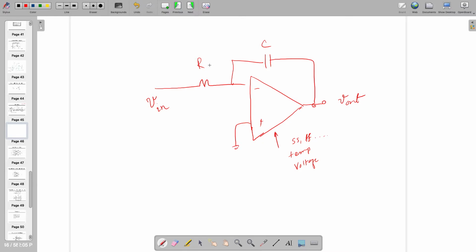Now, the next thing is when you are keeping R and C on chip, how much guarantee is there that this R and C value will be the same? You wanted to design it for, let's say, 100 kilohertz, but for the worst case corner this is 100 kilo. For the best case corner, it's 10 megahertz. Such things you are going to observe, and if this frequency is increasing, believe me, it will consume more power, right? So operation has increased with the frequency. So what are you going to do in that case?